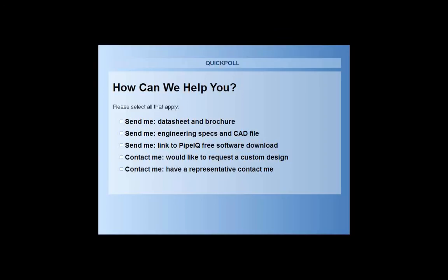They're asking whether within PipeIQ they can have customized angles, for instance, 135 degrees. Is that possible? No, we can't put 135 degrees on angles, but what I've done in the past to create such angles, for example for dome applications, is create a pipe swing and then angle the pipe accordingly.